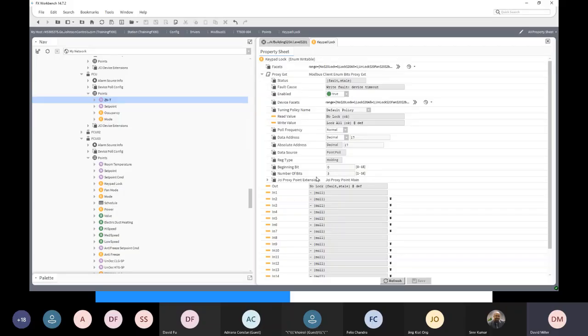So if you've got a device you're trying to map, pick a register where you know what the expected value will be. Another good one is the frequency. For a power meter, you expect frequency to be about 50 hertz, or 49.9 or 50.7, something close to 50. So if you can set it up and get a reading of 50 or thereabouts, you know you've got it right. And once you've got one point mapped correctly, you can use that as your guide to set up the rest of the points.